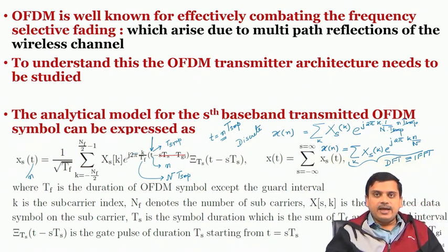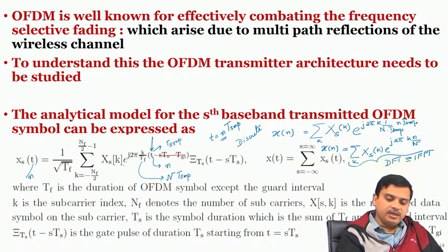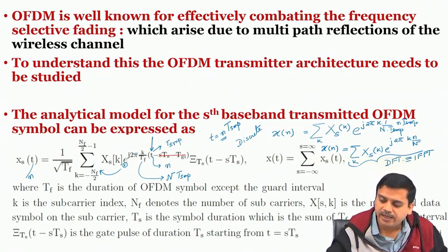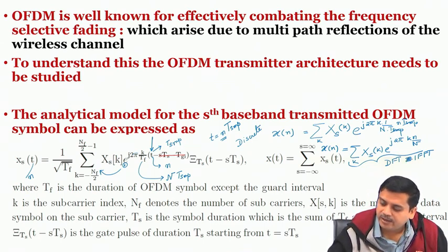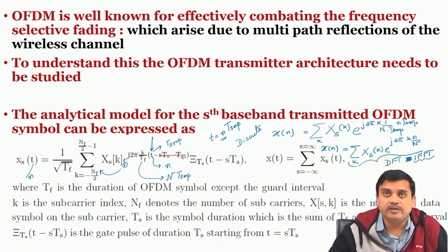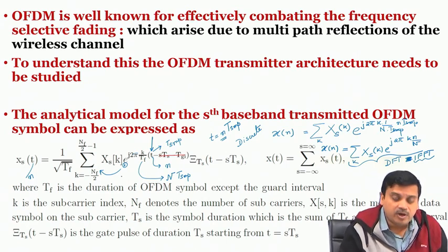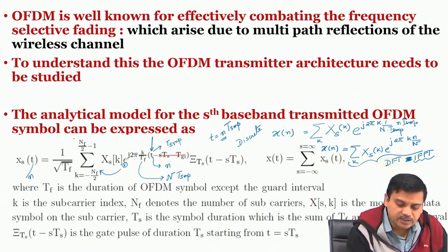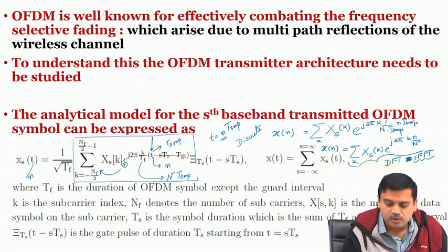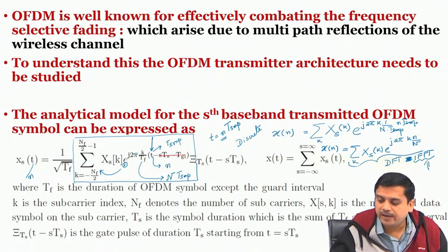So, that means this entire thing can be realized in a completely discrete manner, and the entire set of multiplication operations that was happening here could be replaced by a multiplication and this summation. This huge processing can be simply replaced by a DFT, and the DFT can also be replaced by an IFFT operation, because IFFT is very low complexity, right. So, we have to now visualize this entire expression that is happening over here through the view of IFFT, right.